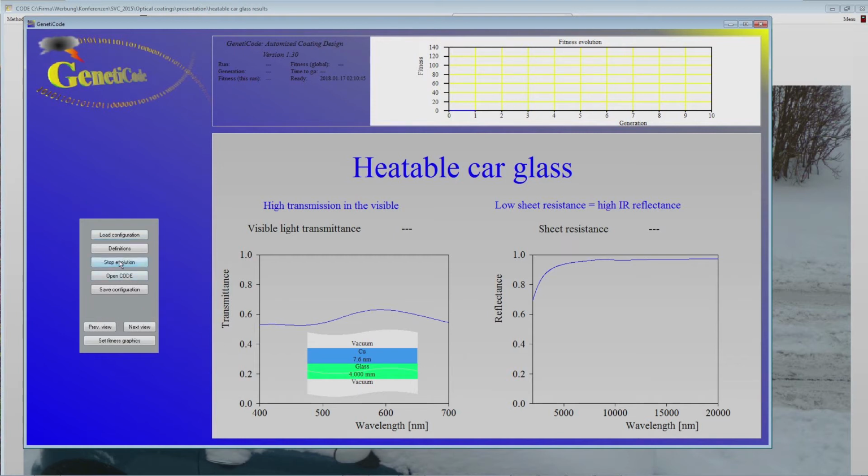In this case, the problem is really simple. It will be very quick, but also not very good. The winner is a layer of copper, about 7.5 or 8 nanometers. Let's see how this goes. The light transmittance is something like 60%, and the sheet resistance is 2.6. That's the best solution, but as I said, not very good. So let's try 2 layers.